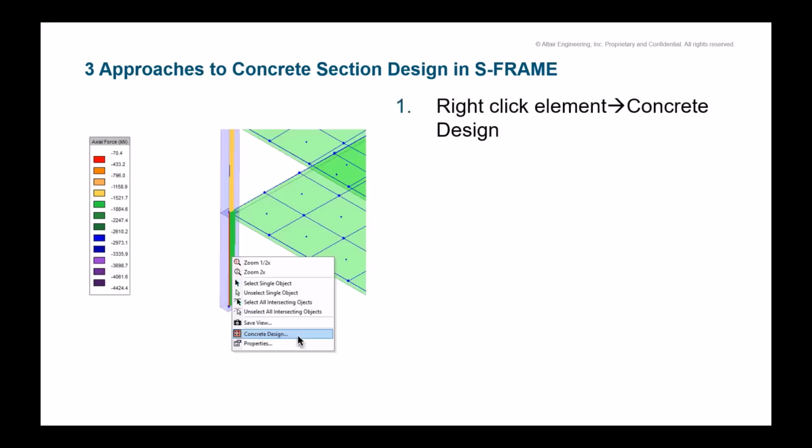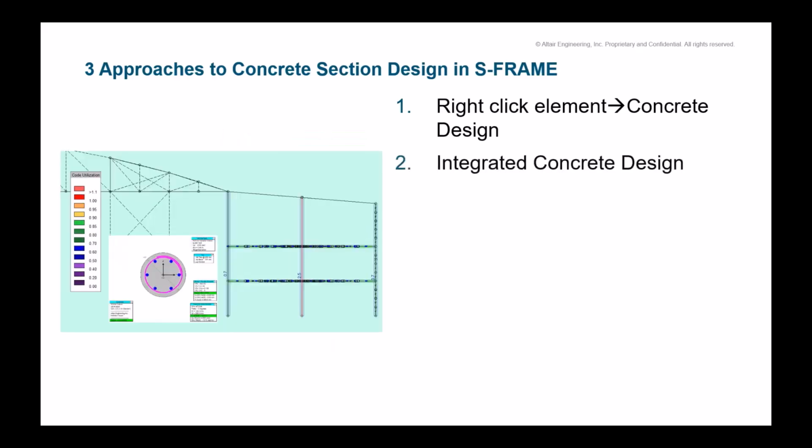When we have these models, we're going to have our elements. And in these elements, after obtaining results for our analysis, we can just right click on the element and then click on the concrete design interface. This will take us into the concrete design modules within S-frame. That is one way to do it.